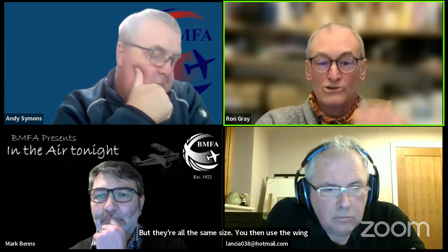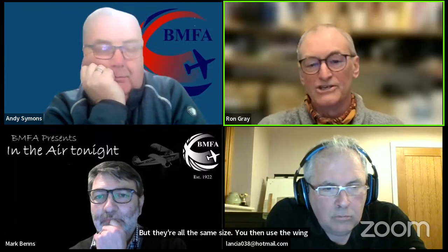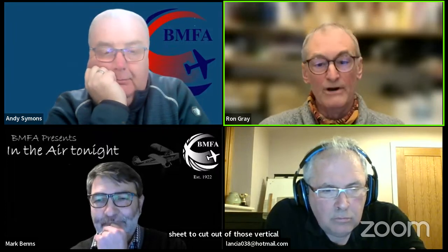So you do that, and you then pattern that along the length of the wing at the spacings that you want, say 50mm spacings, and that will put in your 7, 8, 9 ribs, but they're all the same size. You then use the wing sheet to cut out of those vertical panels that I've just created, and that will leave you with the ribs. So that's in a nutshell how you do it.